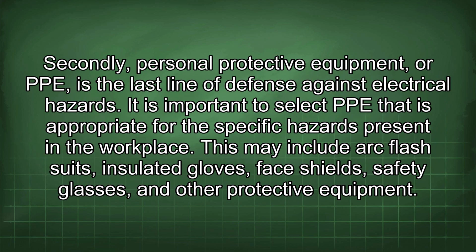Secondly, personal protective equipment, or PPE, is the last line of defense against electrical hazards. It is important to select PPE that is appropriate for the specific hazards present in the workplace. This may include arc flash suits, insulated gloves, face shields, safety glasses, and other protective equipment.